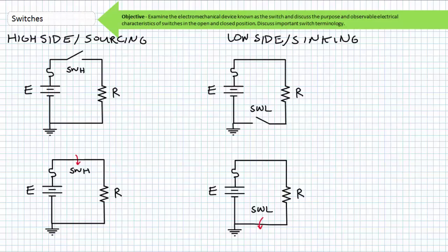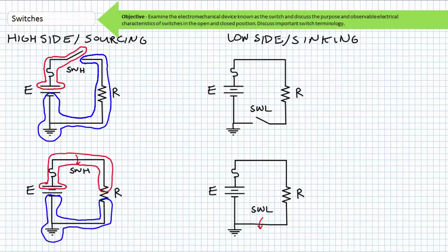In a high-side switching arrangement, when open, the switch experiences all the voltage drop. Both terminals of the electrical load are at low potential, and there is no voltage differential across it. The electrical load is de-energized when the high-side switch is open. When the high-side switch closes, both terminals of the switch are at the same high potential. However, there is no voltage differential across it. The electrical load experiences all the voltage drop. The electrical load is energized and experiences flowing current.